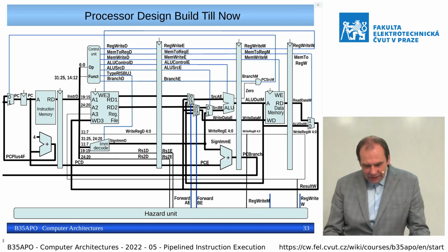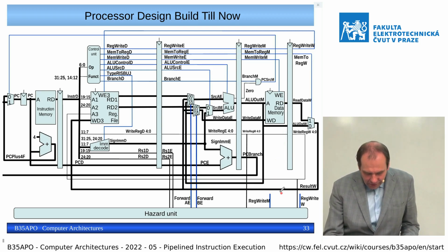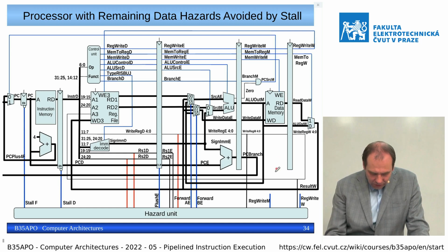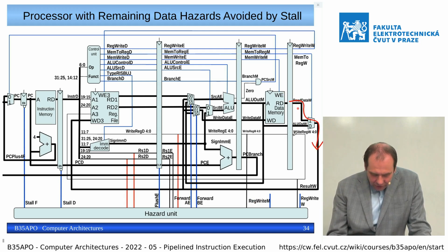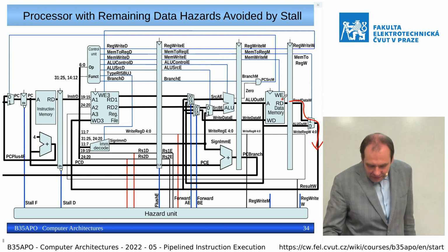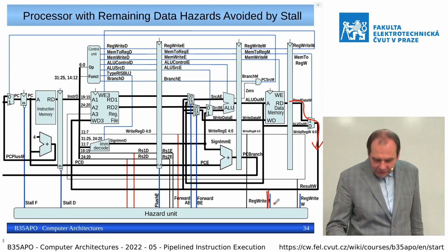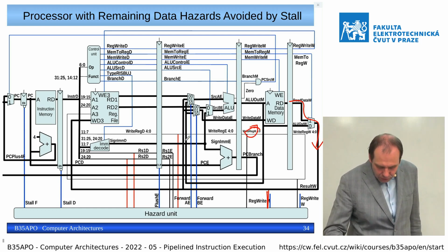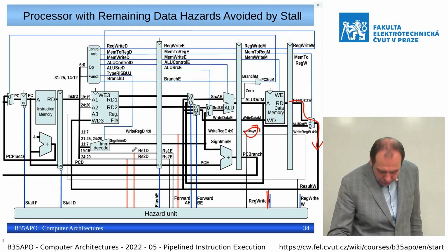So for this case, when there is a write to the register data from the reg write M, basically, if we know that we need to go there not from the bypass, but in the next clock cycle from the output of the memory, then we can resolve it 1 clock earlier. So basically we can resolve it at the decode stage.